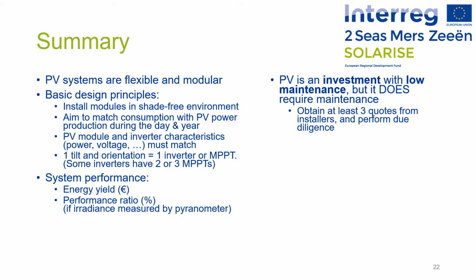Important to remember with all of this is that PV is an investment with low maintenance, but it does require maintenance. When it comes to asking quotes, you need to obtain at least 3 quotes from installers and perform due diligence on those installers. And module cleaning is generally not needed. And as a reminder, do not spray water on those when the PV modules are hot.